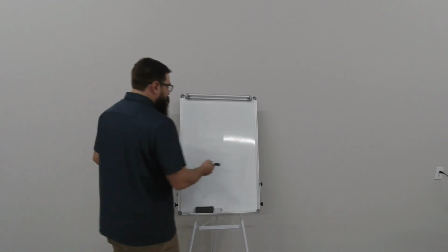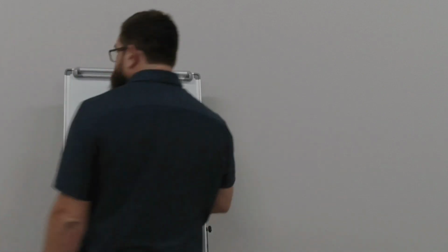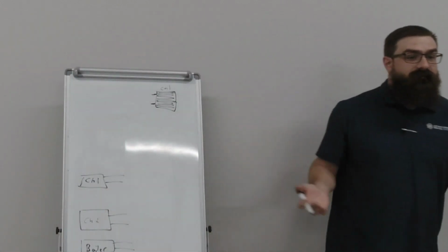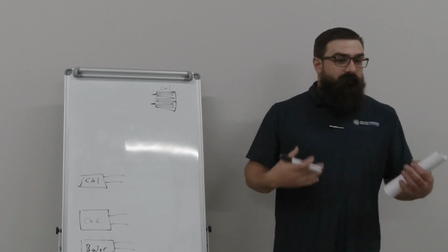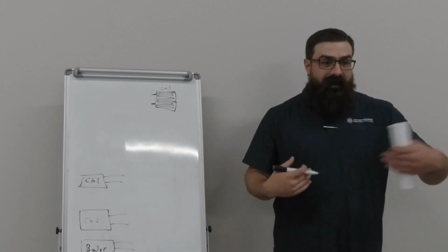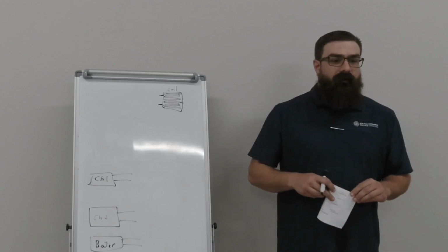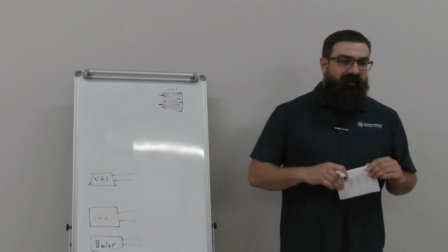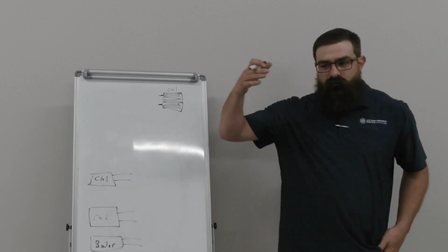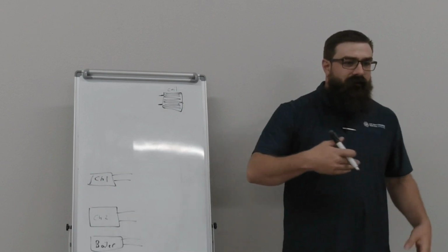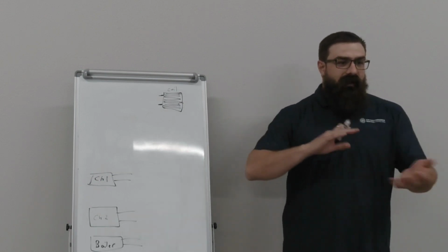All right. So this is our air handler. Everything has a supply and return, no matter what kind of system it is. 2-pipe, 4-pipe, doesn't matter. Every device has to have a supply and return. It has to have inlet and outlet. One thing that a lot of people struggle with, me included, is supply and return and what the definition is. Because when you come from unit to chiller to cooling tower to condenser water to evaporator, it flip-flops, right?